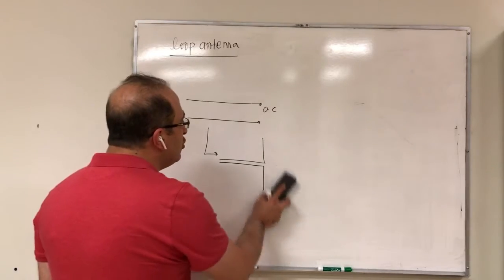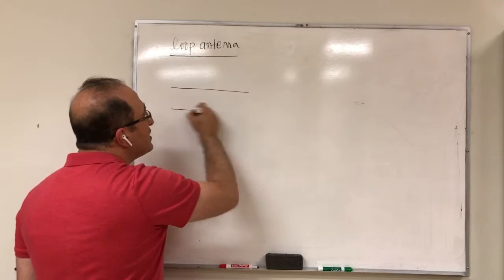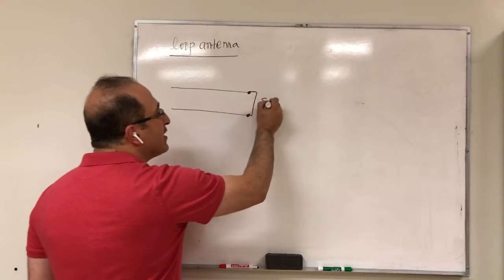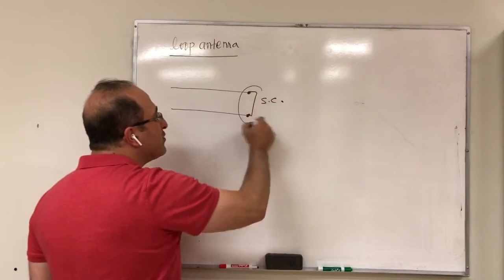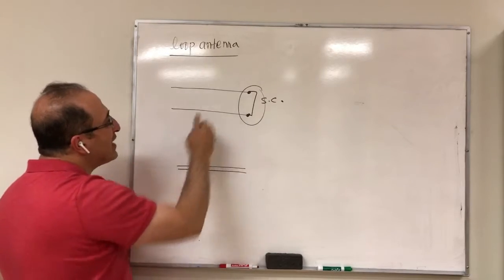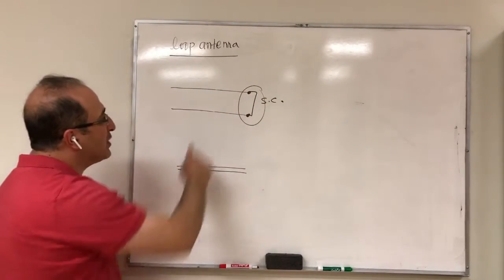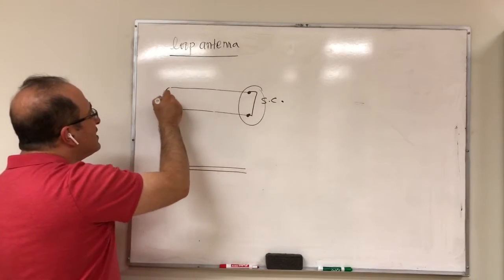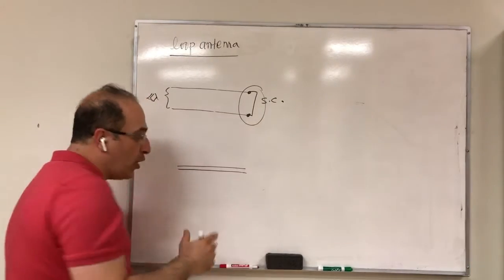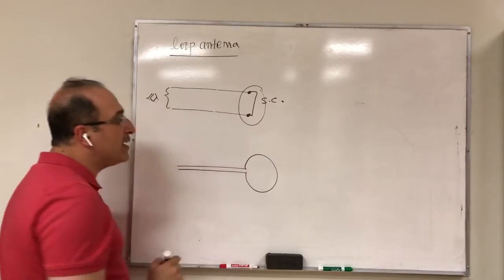So when it comes to loop antenna, the situation is reversed. Now this time this is not open circuit, in fact this is short circuit. So now you take part of that and then you make it. So this is the transmission line, the same as that. Here I emphasized the separation to create my short circuit. But remember, in transmission line, this separation is much smaller than lambda. So then I'm going to open it up.